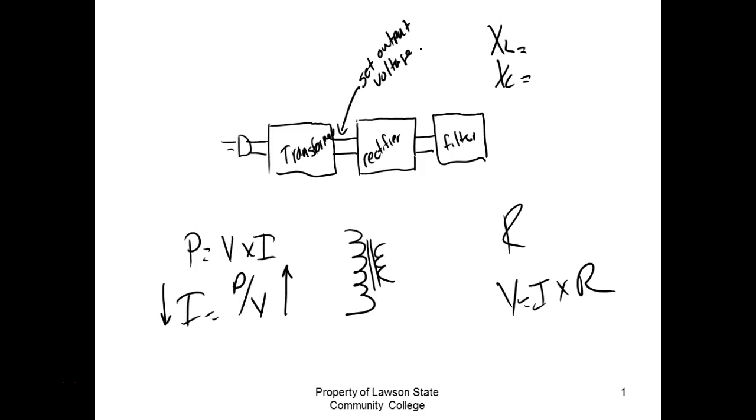So we have 208 here. The ABB robot, even though it runs off DC, needs 440. So what do we have to do? We have a step up transformer for both the ABB and the big ones. They run off 440, so we have a step up transformer. You can't say they step it down. They're going to step it up. But that transformer sets your initial output voltage.